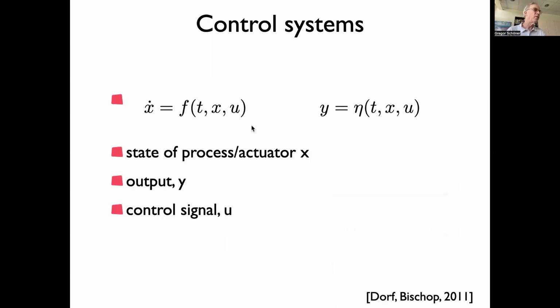So mathematically, you have a model of your plant. They call that the process in some cases, but often also plant. That can typically be a large differential equation, with a lot of vector values here. That would include also the physics of the actuator. It could be explicitly time dependent in some cases, when there's some external way of driving, some external thing that changes.